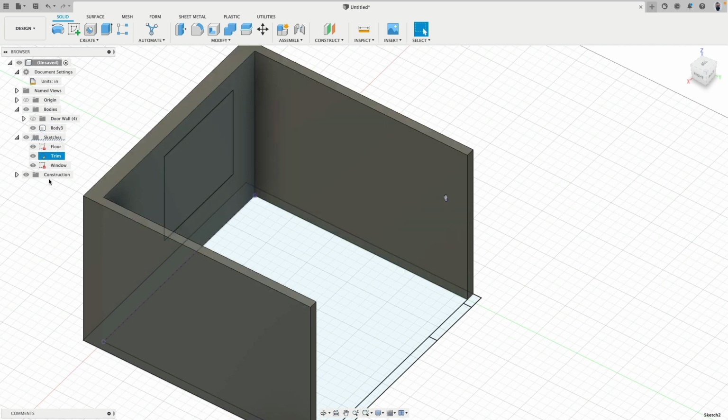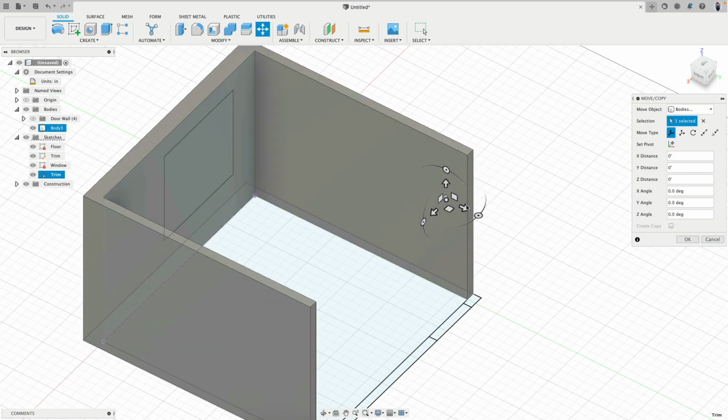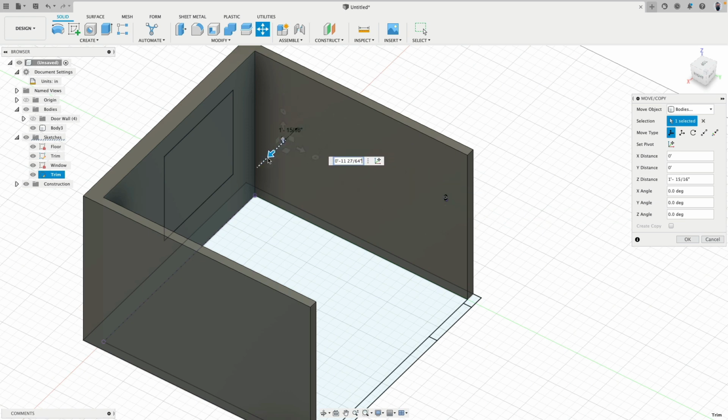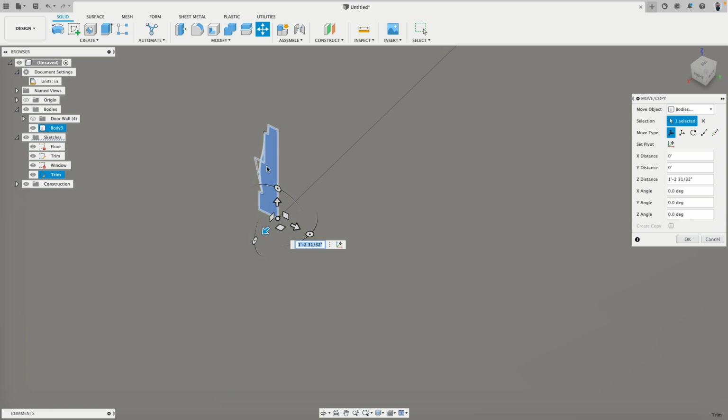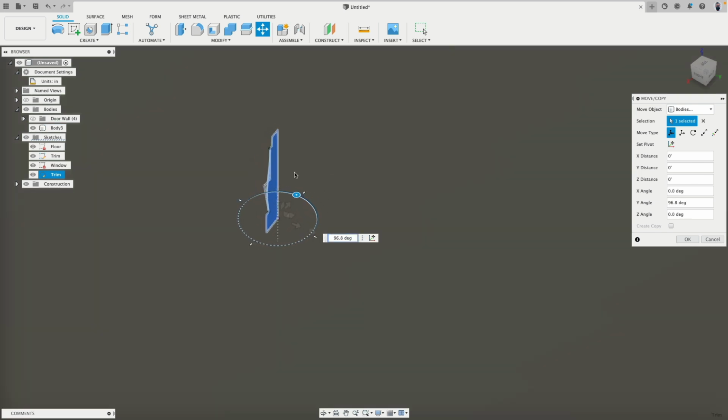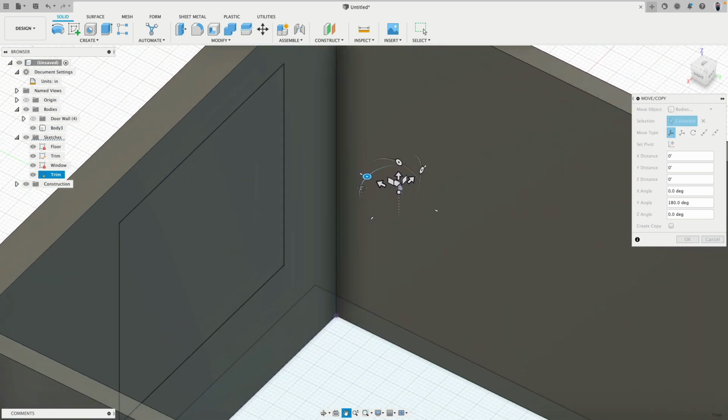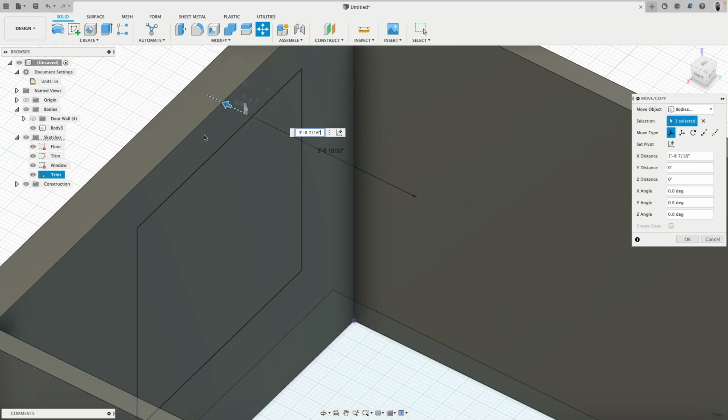So what can we do now? Well, I can select this trim body, copy and paste, and then move this to somewhere else. So the copy and paste on the Mac was just Command key C and V after I had the trim piece here selected. So on the PC, pretty much it will be the Control C and V. And there we can see this has to rotate. So I'm moving and rotating it. Very good. So I can get this closer.